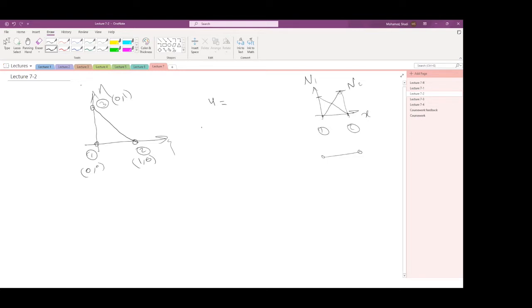Now, the same behavior would also happen in 2 dimensions. The first shape function, which is associated with the first node, is going to be 1 at the first node and then 0 at the others. I'll try to draw it. I'm struggling to draw things in 2D, so it will be even messier in 3D. So this is xi, and this is eta, and think about this as shape function number 1.